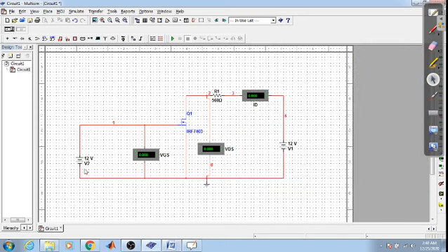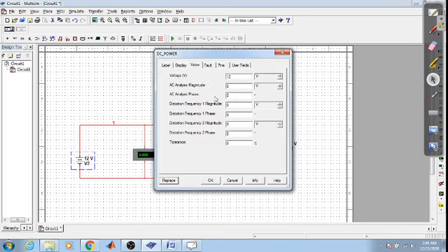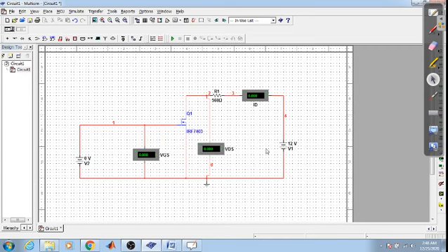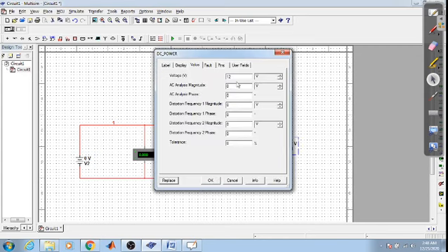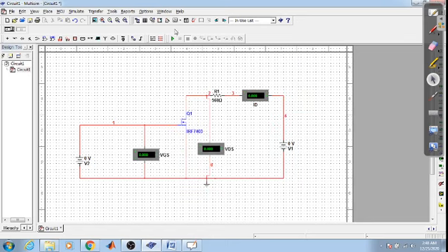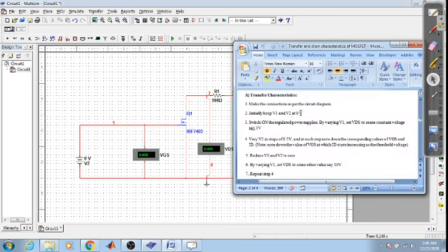First you make all the voltages 0, you make this 0, again you make this voltage 0, click on OK and try to run the circuit. So everything is set to 0. Now stop it, and let us go to the second step. Initially keep V1 and V2 at 0. So we have done that step right now.